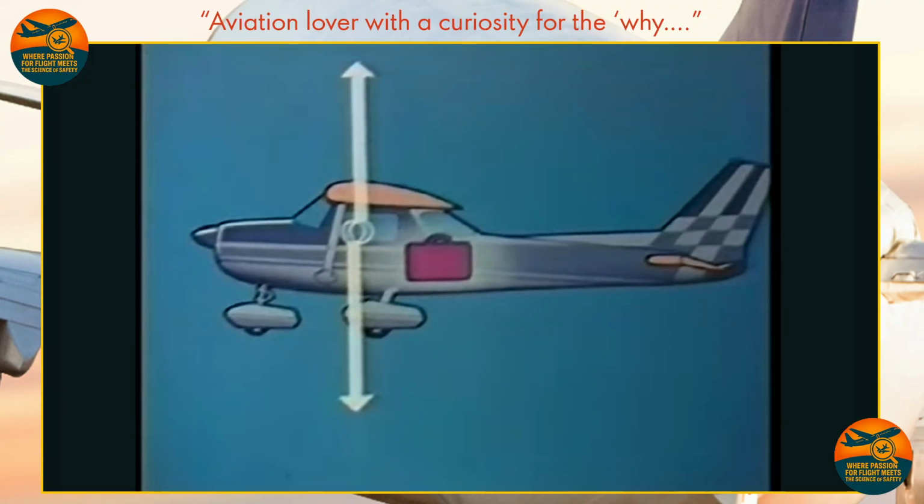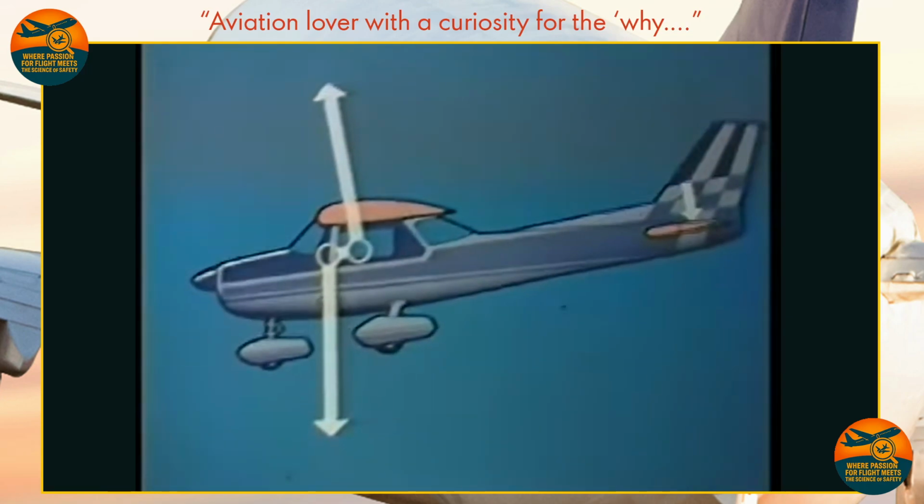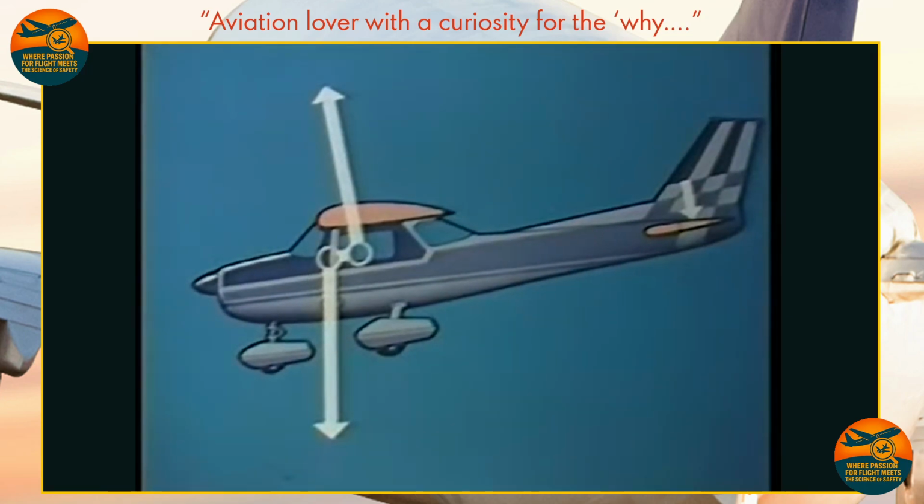The aeroplane can thus maintain level flight despite the fact that the center of gravity is misplaced, provided it's still within the design limits of the aeroplane and without the pilot having to hold the aeroplane level manually. In the same way, if we need to increase the download on the tail, we can use the trimmer in the opposite sense.